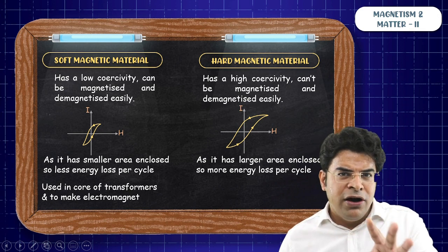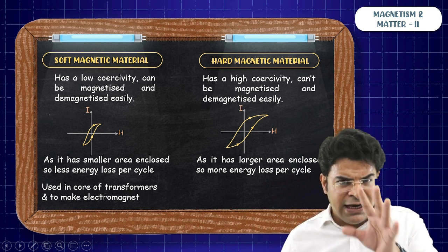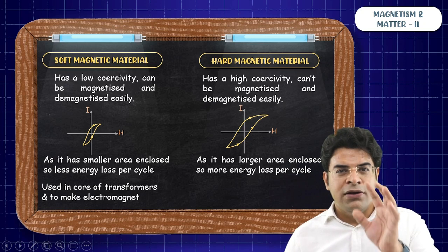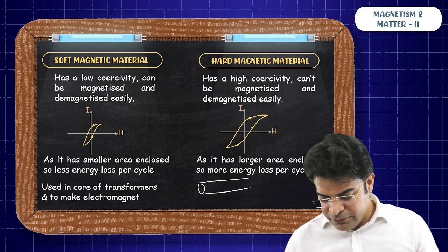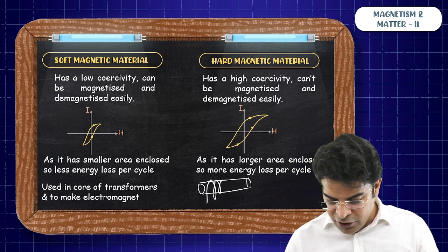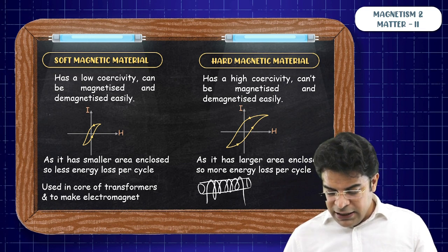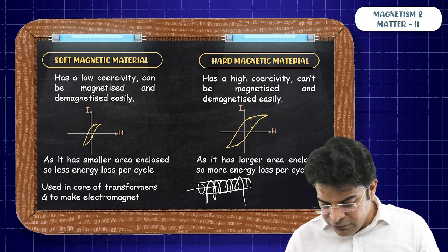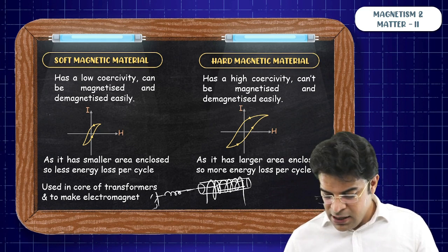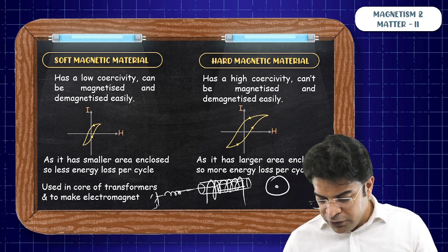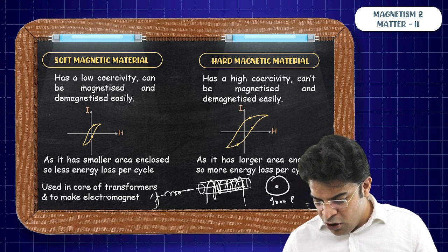Have you ever heard of the usage of electromagnet? Let me tell you one usage which is used for doorbells. We take a solenoid, we wrap a wire around it, and then we put an iron piece within the solenoid, and this iron piece is connected to a spring. And here we have placed an iron gong.